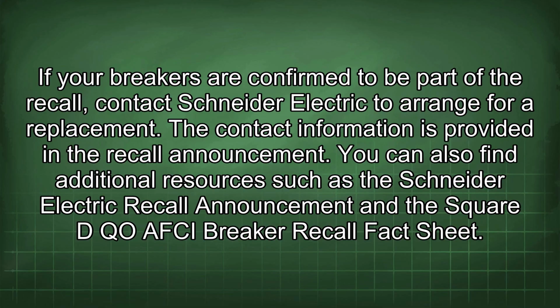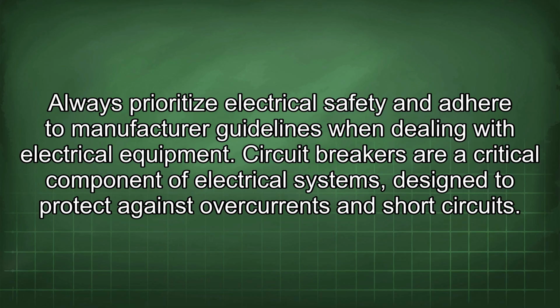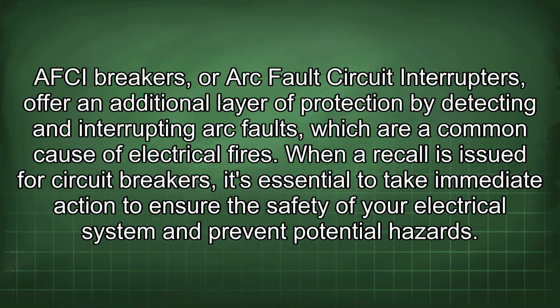You can also find additional resources such as the Schneider Electric recall announcement and the Square D AFCI breaker recall fact sheet. Always prioritize electrical safety and adhere to manufacturer guidelines when dealing with electrical equipment. Circuit breakers are a critical component of electrical systems, designed to protect against overcurrents and short circuits. AFCI breakers, or arc fault circuit interrupters, offer an additional layer of protection by detecting and interrupting arc faults, which are a common cause of electrical fires.